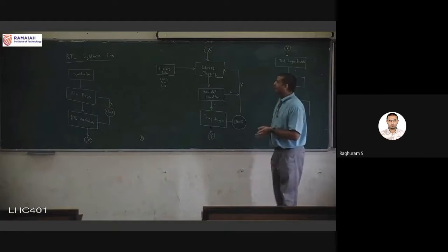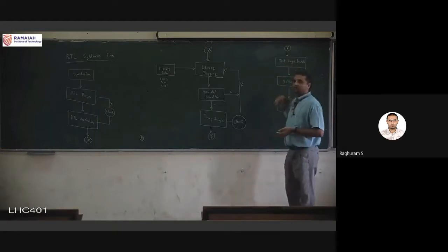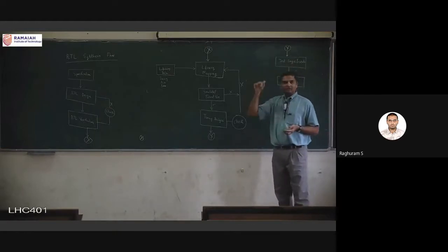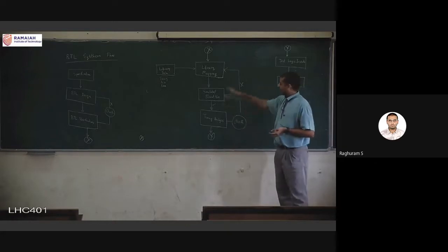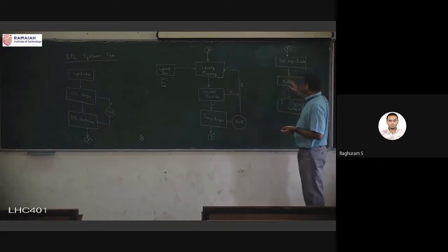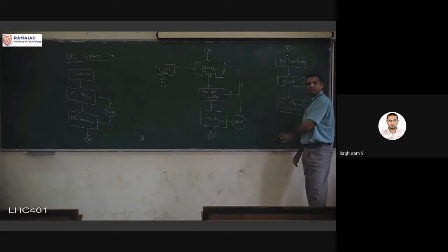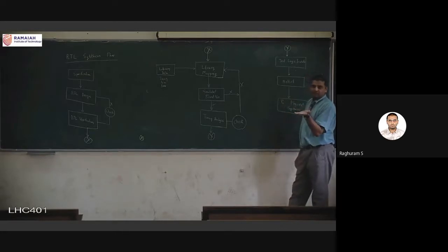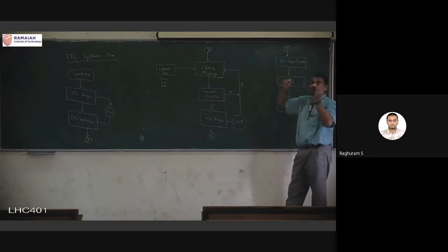Okay, and in that first silicon, now the test logic is already inserted. We are not inserting it now. During the design phase itself, we are having this netlist. This is going for physical synthesis. Back-end design happens, tape out happens, and it comes back to me. That is the first actual silicon implementation of my design. And now this comes into the picture. It's not gone to the end user. It's still with me, the designer.